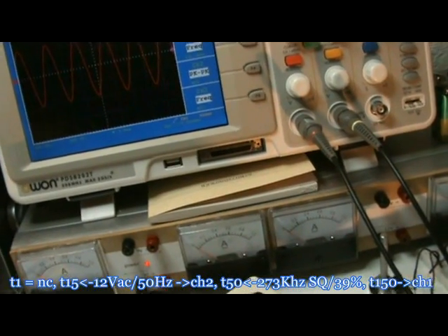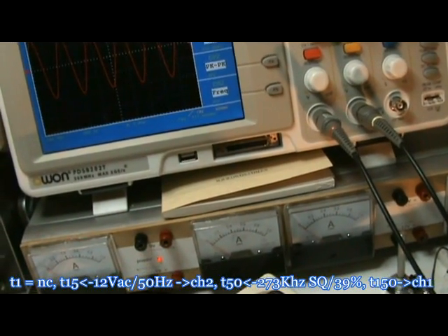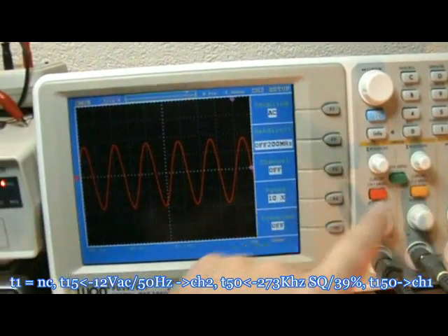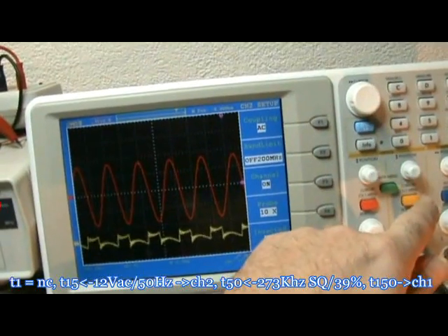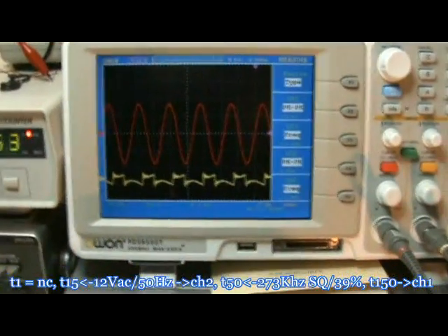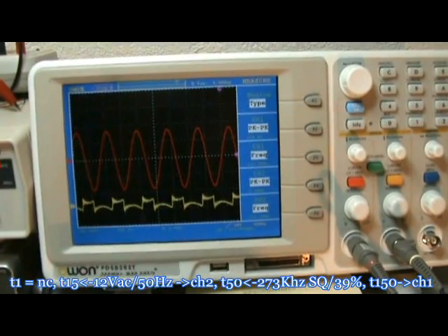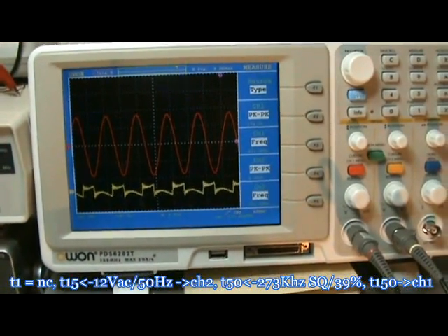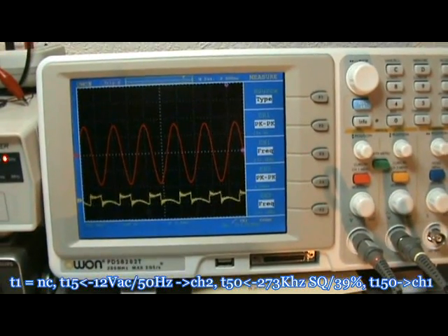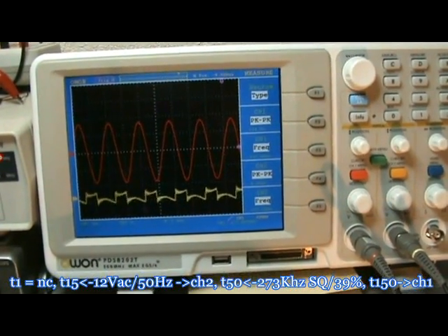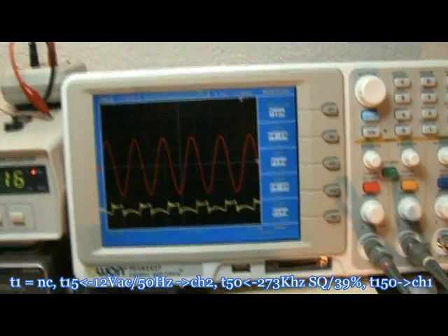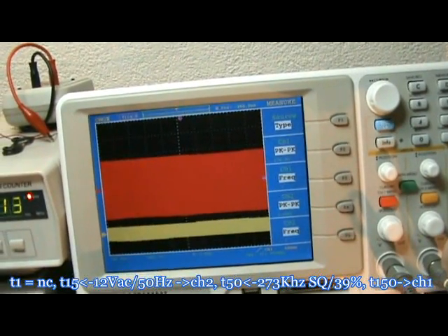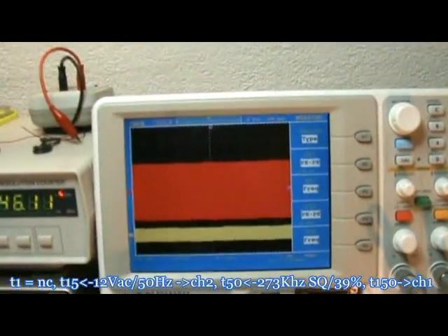See what kind of signal I've got there. Put my other probe on it. And you see I'm measuring now the yellow probe on the 15 turns, and you see I have the square wave from the function generator put on the 50 turn coil, nicely being transferred. But I'm looking for 50 hertz now.